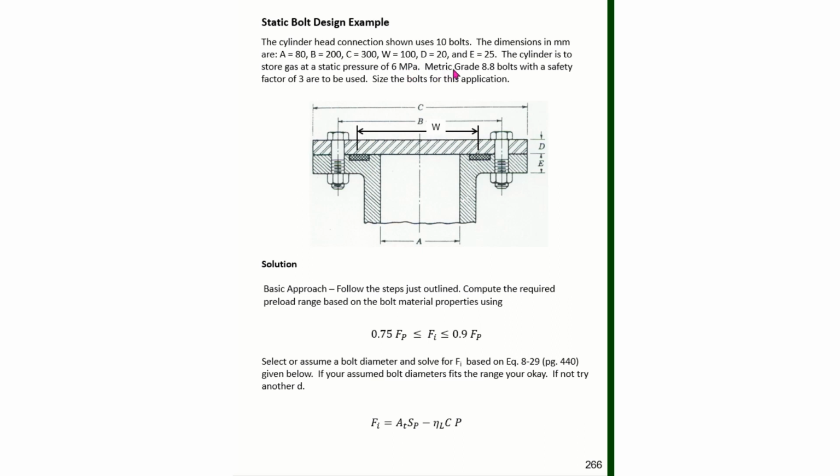We're to use metric grade 8.8 bolts with a safety factor of 3, and we need to size the bolts for this application. One of the things that we need to consider first is the force in the bolts. We need to determine that force by understanding the pressure loading from the cylinder cavity.